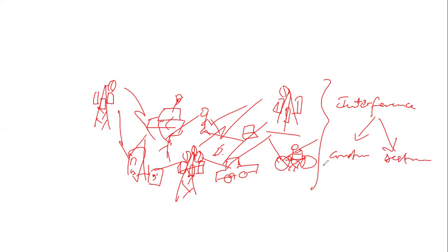Okay, so in other words, recall we have either constructive or destructive interference, right? So it's either the signals add up together and then the strength or the power of that signal amplifies, or the signals cancel out and then we have a zero zone. So that's total loss of signal. And then we now begin to deal with channel fading issues, okay? Then we want to address this problem.